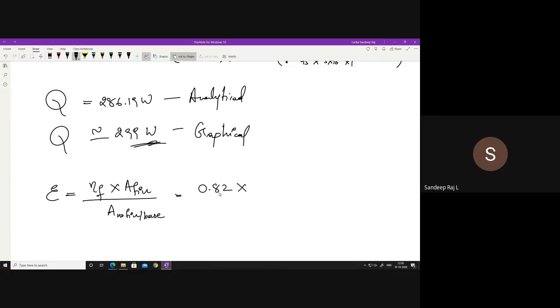And the area of the fin, it is again 2 times 1, I'm writing the perimeter first here, 2 times 1 plus the other side 3 into 10 to the power of minus 3 into 1. Perimeter into length. And the area in the denominator will be 1 into 3 into 10 to the power of minus 3. So now you tell me what is the effectiveness formula.